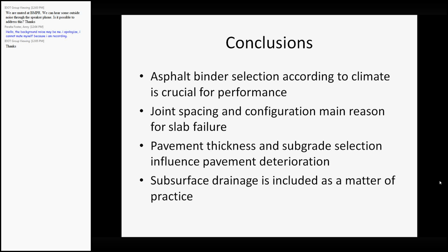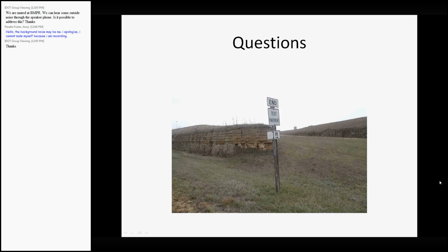We saw how in this specific project the underdrains didn't show any tangible benefits, but through other studies we have concluded that preventing the subgrade from saturating is good practice. So we continue looking at these sections to date, and we believe that pavement design is an ever-changing process, and these sections will continue to give us very important information. So I hope I didn't bore you guys to death. I'll take any questions if you guys have any.